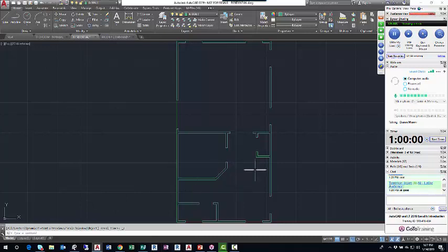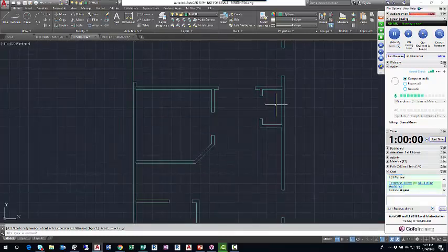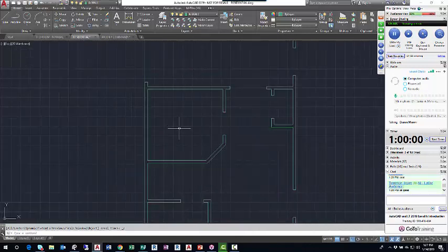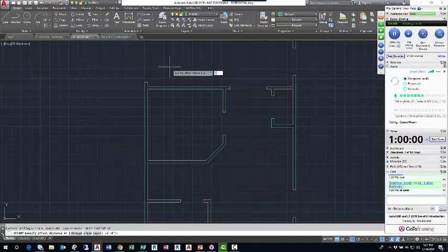In the 4-day version of the class, we create like a whole floor plan. And in the floor plan, the small closet and the big closet both have shelves. I'll use offset, a 1 foot offset specifically, and I'll offset the back line of the small closet, and I'll offset all three of these inside lines of the big closet to create the appearance of shelves. All right. In the small closet, I'm done. I don't need to do any more work there.